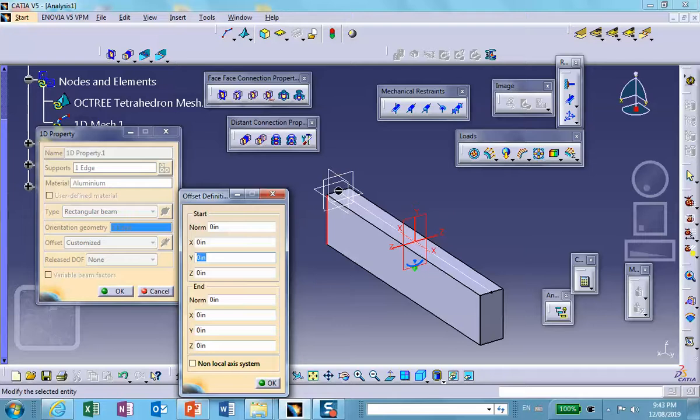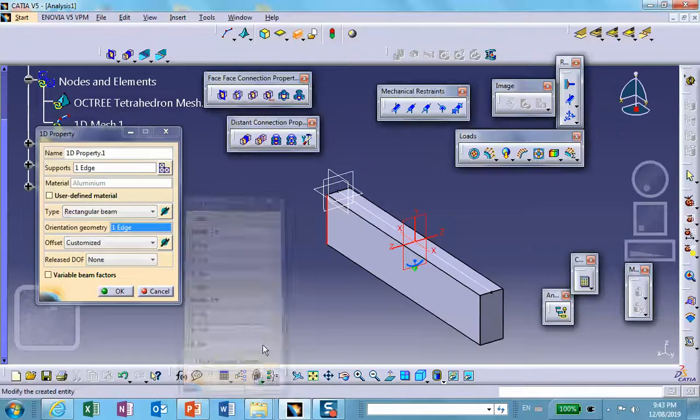You can offset them by different amounts, but in this case, I want to move the whole thing up by 1 unit. And 1. So the left side of the beam internally is assumed to be 1 inch above where it is now, and the right side of the beam is also 1 inch above. You will not be able to see that on the screen, but internally it's going to be taken into account. All right, and that's it.